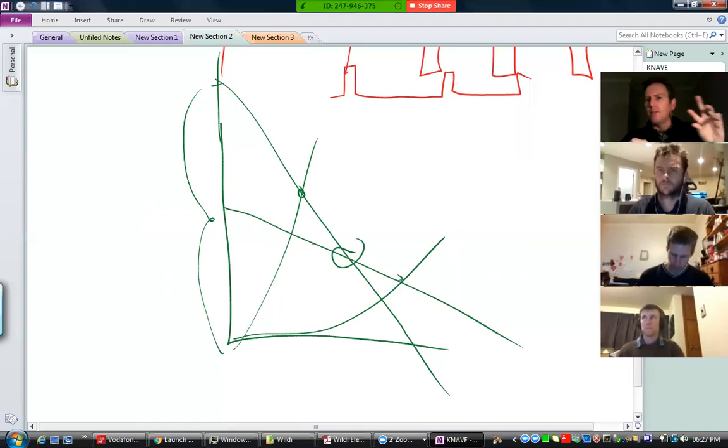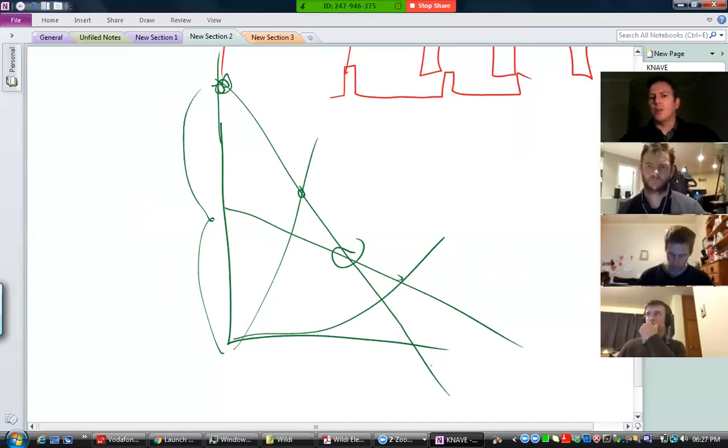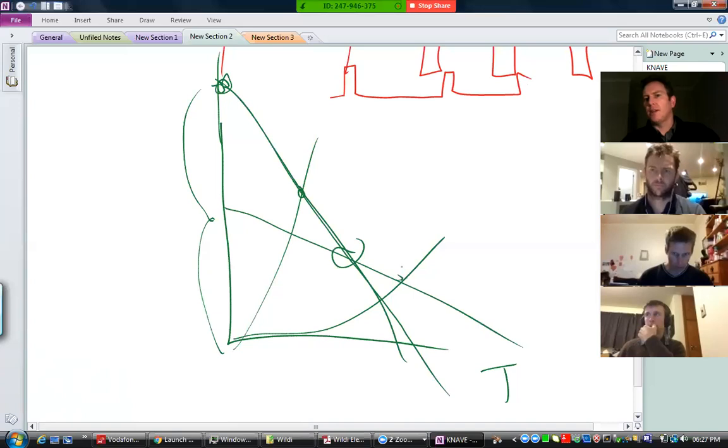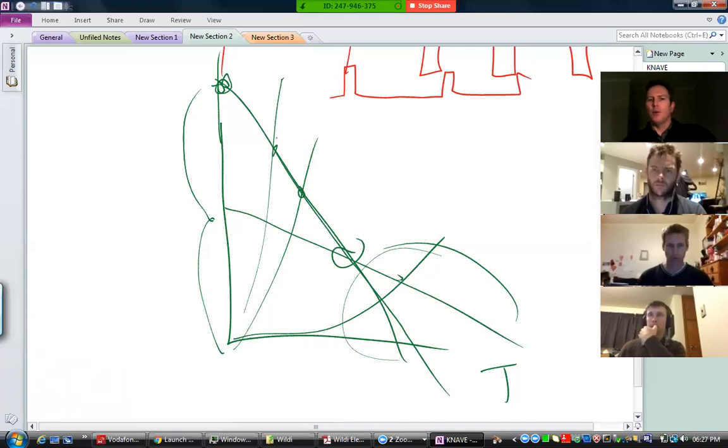Basically, in the field winding scenario, when you reduce the field, the speed actually goes up for the no load case. But reduced flux can also mean you need more amps to achieve a certain torque. If you want a high torque, you've got to feed lots of amps through it, and then the graph drops off quite steeply. Even with a reduced field, you can get the thing slowing down in that region. But if you've got a load which allows it to run fairly close to no load speed, not that much torque, then you will get an increased speed when you reduce the flux in that field by putting a resistor in there.